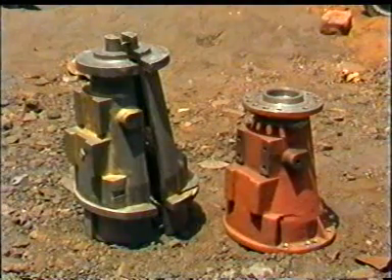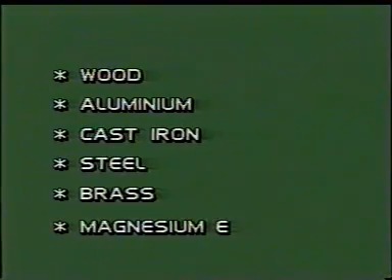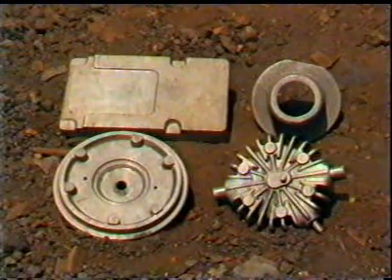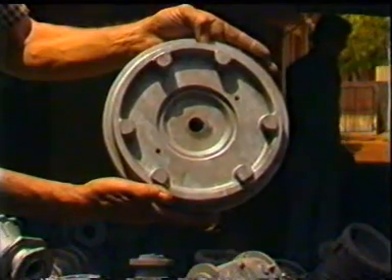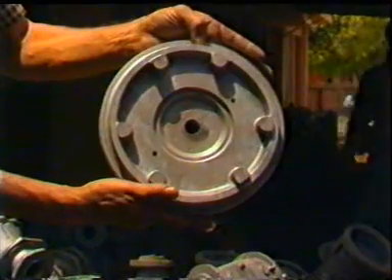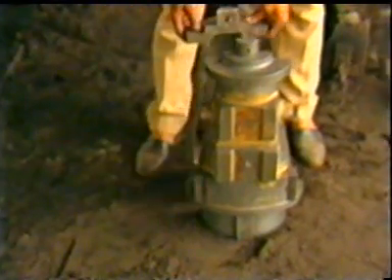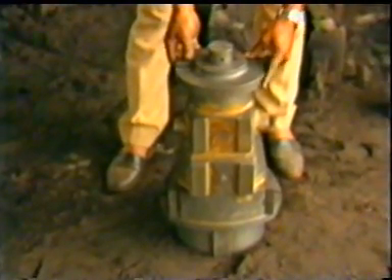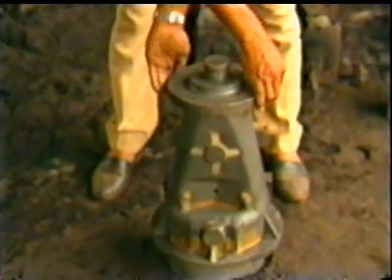The patterns are made from wood, aluminium, cast iron, steel, brass, and magnesium, etc. Pattern may be solid or split type. Patterns are generally made on precision machines.